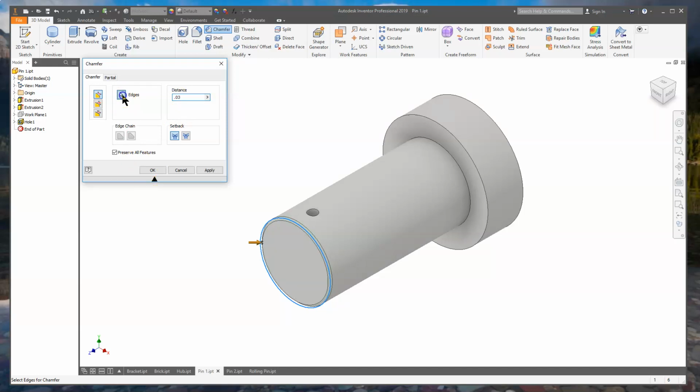Put that chamfer on. I go to the face here and click on the edge. Go to that edge and that edge. Success. There we go. All right, here's the other thing: if I'm going to put a pin down through here, having that opened up a little bit instead of that blunt edge will help me lead that in there a little bit. Let's see what our 30 thousandths does on that. Does that open it up a little bit? Make it easier to get something in?